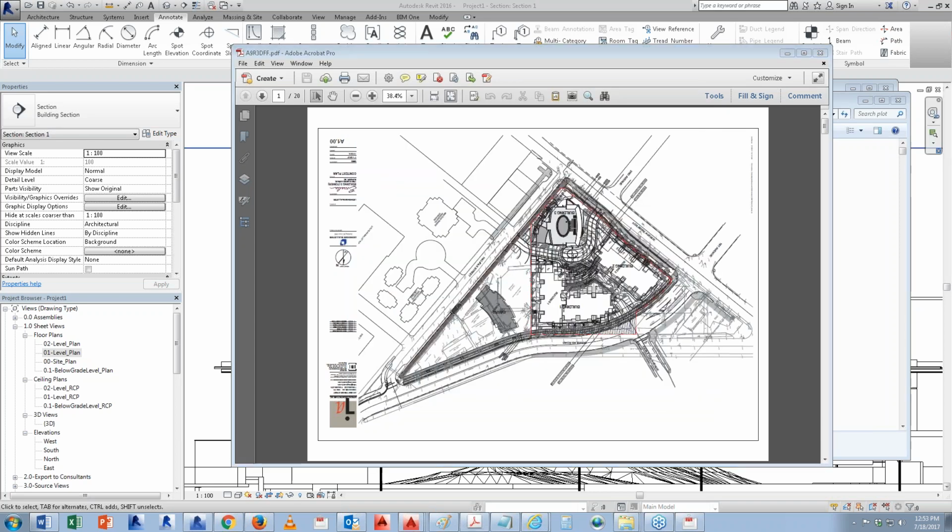If you have any question, did you link to SketchUp or CAD? It's basically, okay, SketchUp files, Revit is able to pick up SketchUp files in the newer version. It's just the older version, I just export them out. So for this question, I just export and import, link CAD, okay? So basically, that's the question I have.